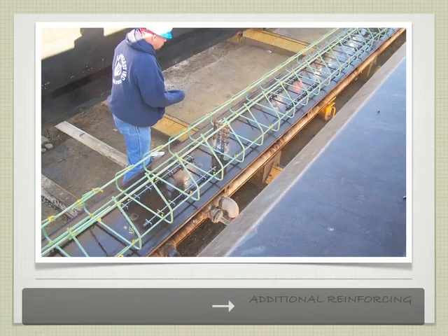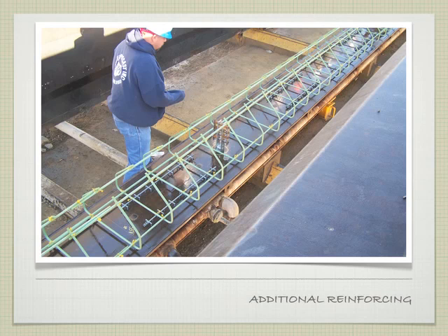So if we look down inside, we're putting our reinforcing into place. We don't have those tendons strung yet. It's easier to put these in first. Notice we do have the chairs, keeping these nice and consistent.